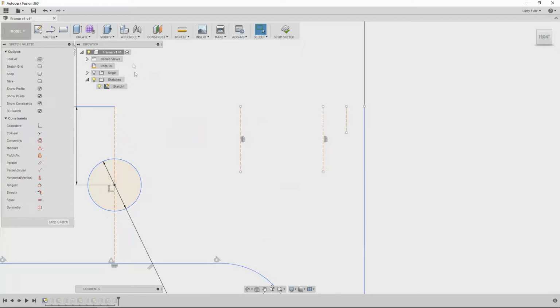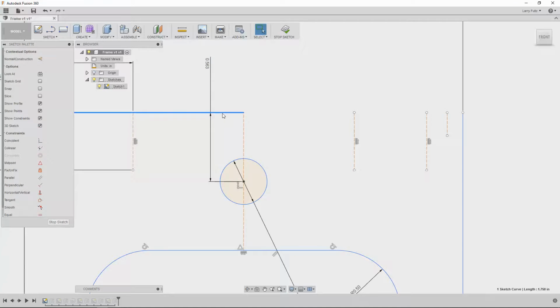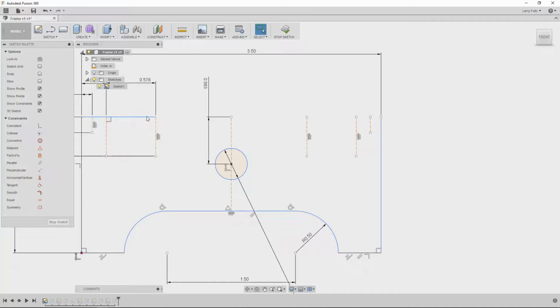See what I was talking about there with that line that was underneath the line? We had a shorter segment right here and a longer segment on top. Well, if you create a dimension, are you dimensioning to this line segment, or are you dimensioning to this line? Because you're only grabbing an endpoint in many cases. So we want to reduce the chance of error by always getting rid of our orphan geometry. So we'll go through and delete all of these sketches here.